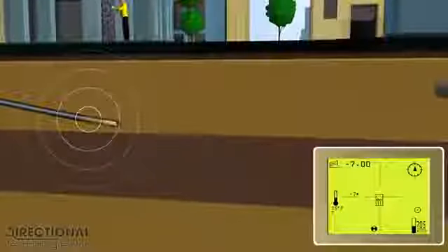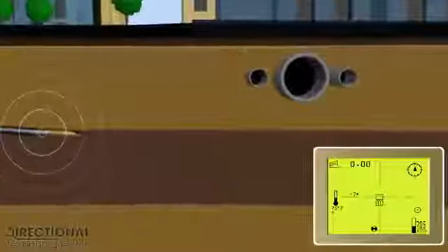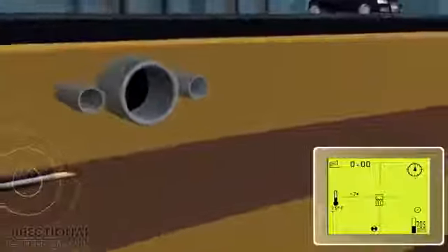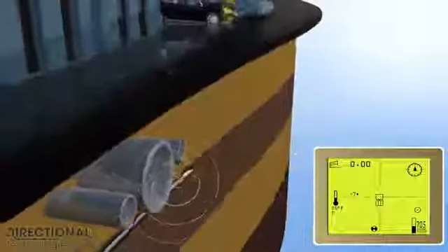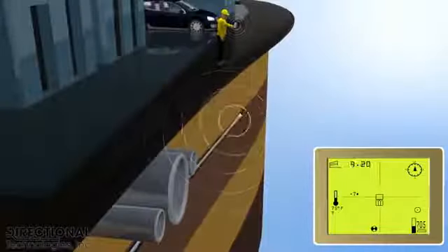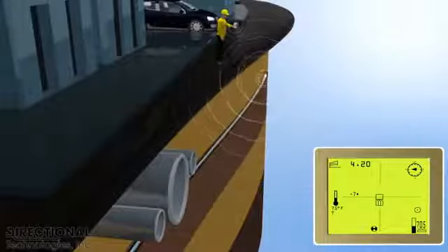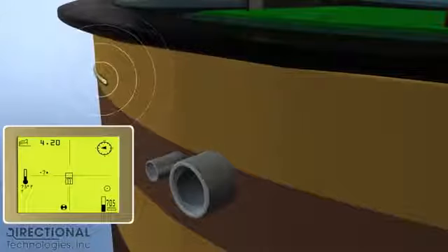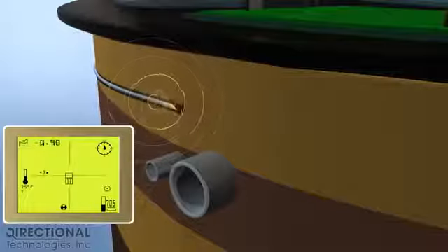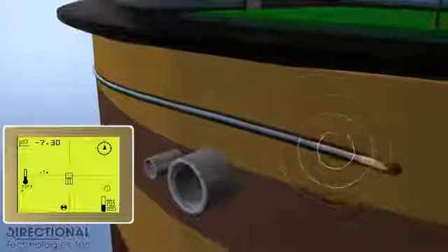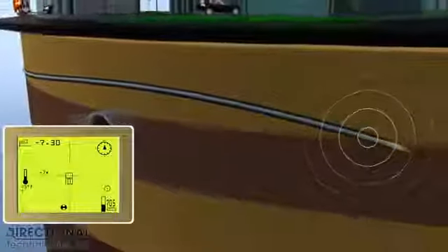The directional drill bit is tracked by a sonde, or radio detection device, housed within its extended connection to the directional drill pipe. The depth and pitch is sent to the surface and received by the walkover locating device. The locator then gathers and interprets the information and gives directions to the directional drill operator on which way to